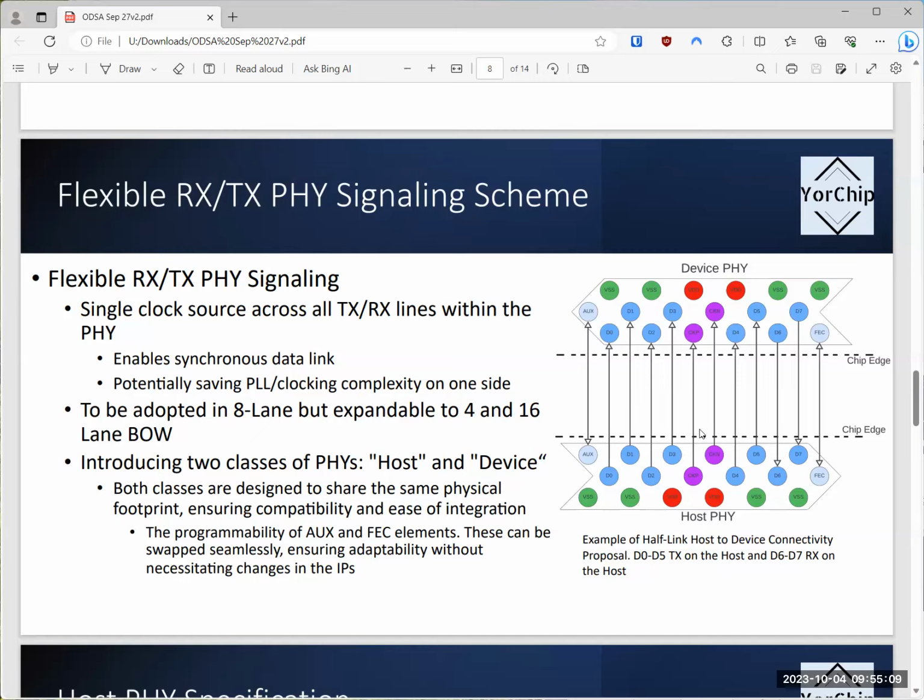In terms of backward compatibility, the IP reuse, the physical IP reuse, and the IP design, that is another side question. So that's my view. And also the half-clock edge shifting is introducing another timing sign-off mode that I need to consider.